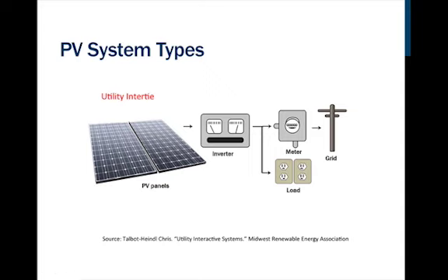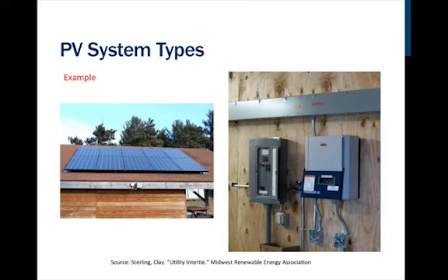It just doesn't work. Once the grid is up again, the inverter will monitor that for 5 minutes. If everything's good in voltage and frequency, it will relink with the utility grid, and your system is up and running. On the pro side of this type of system, it's the least expensive type of system out there to generate power for your home, and the most user-friendly.